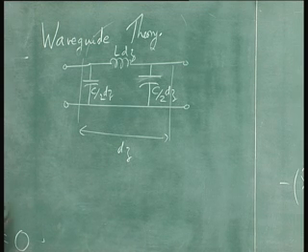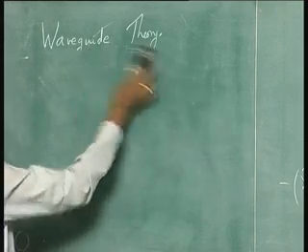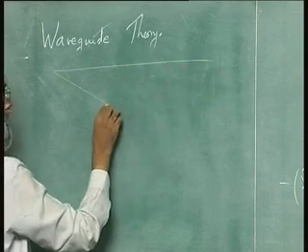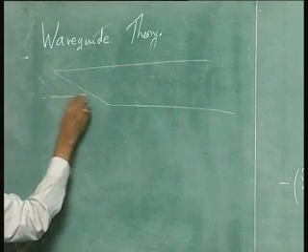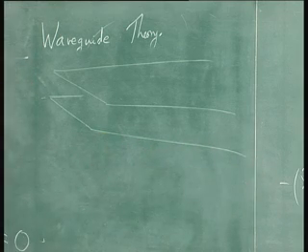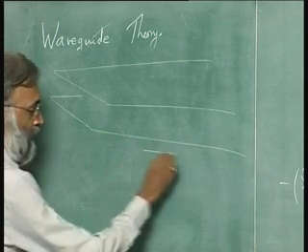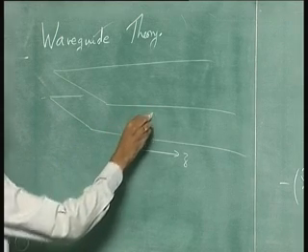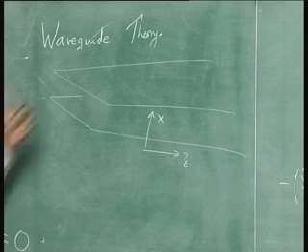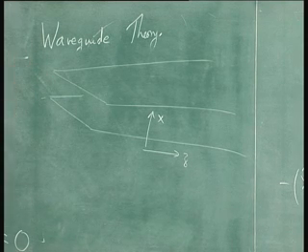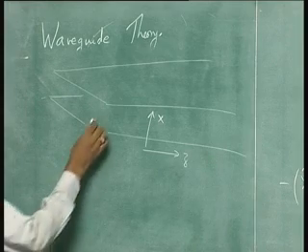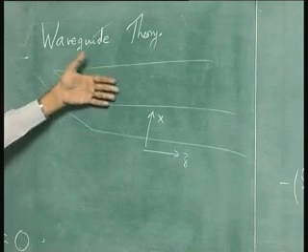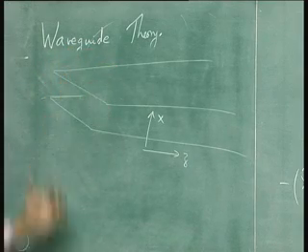Well, the way to look at it is as follows. Imagine that we have a parallel plate capacitor which is very long. This direction is Z, and this direction, the direction between the plates, is X, and we do not care too much what is happening in Y. So we have again the possibility of a TEM wave, because we can solve for the capacitance of this arrangement.